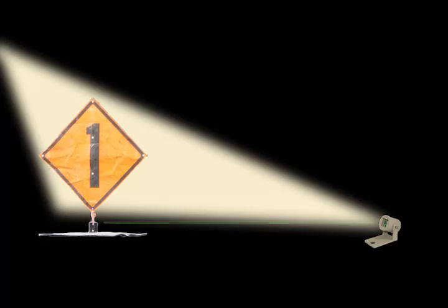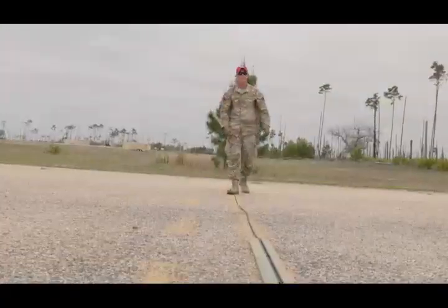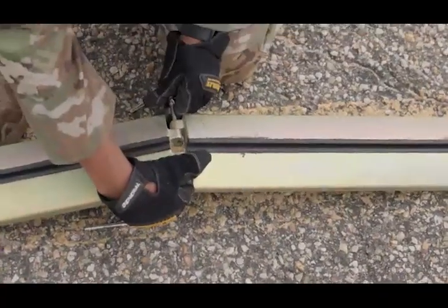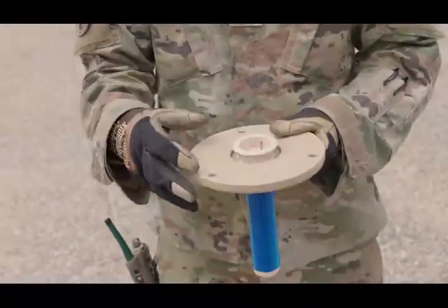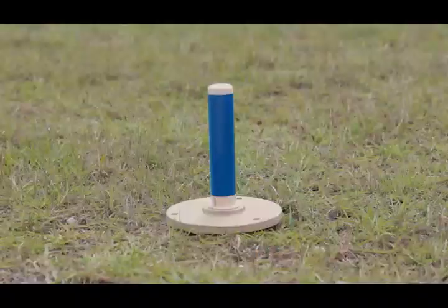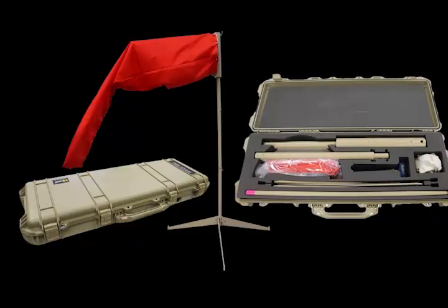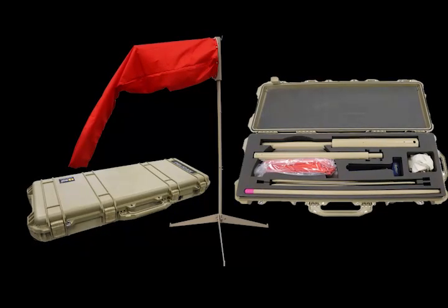The distance remaining marker light is placed in front of the sign, 8 feet away, and angled to illuminate the sign. Cable protection strips come in 42-inch sections. They have a center slit for cable protection. They interlock to keep pieces stable. Taxiway reflectors are 2-piece interlocking cylindrical posts with 360-degree visibility. The wind cone comes in 9 pieces, made of aluminum, and is quickly assembled and stored.